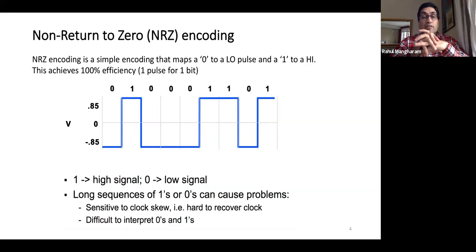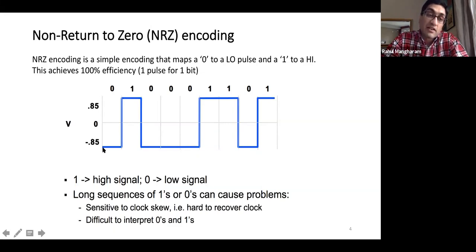But clocks can have other problems. Who can tell me what other problems a clock can have? So one is an offset, what is the start? The offset just means that this was a start of the transition from a 0 to 1, and I just detect that start a little later because it took some propagation time.